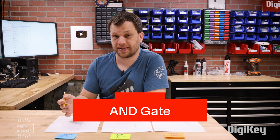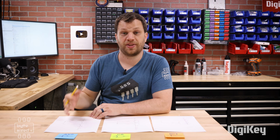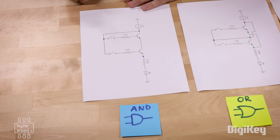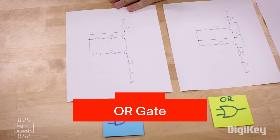Logic gates aren't just some mystical devices that appeared out of nowhere. They're actually made out of transistors. To show you what I'm talking about, I've drawn a schematic for each of these types of logic gates. First, let's take a closer look at the AND gate. Like I said, it's got 2 inputs, and on this schematic, those inputs are represented by 2 different switches. The AND gate has 1 output, and on the schematic, I went ahead and connected that output to an LED.